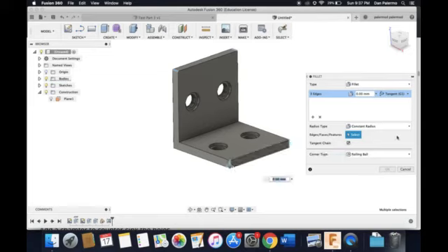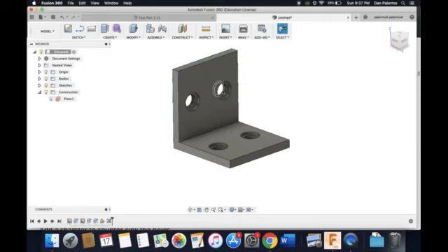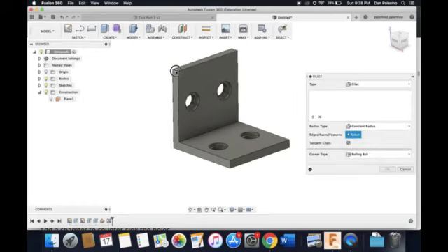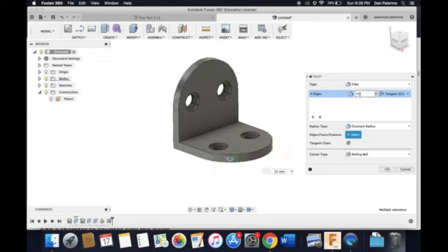that, and that. Okay. Now, I know that I'm 30 millimeters across. If I choose this fillet radius to be 15 millimeters, guess what? 15 and then another 15 there creates 30. Oops, accidentally. Sorry guys, I accidentally pressed my mouse button there, so let's go back to Modify, Fillet, and choose those 4 edges. If I choose 15 millimeters, it's actually going to create a perfect half circle anyways.